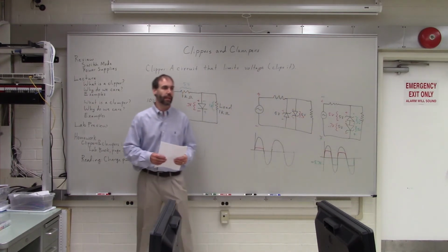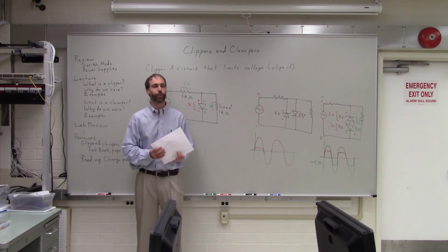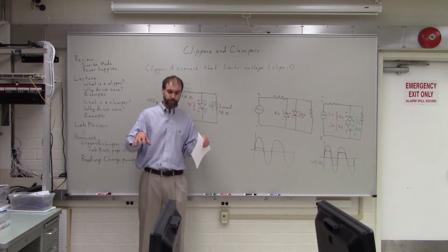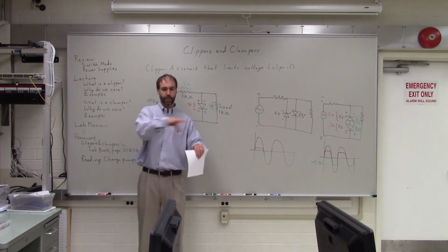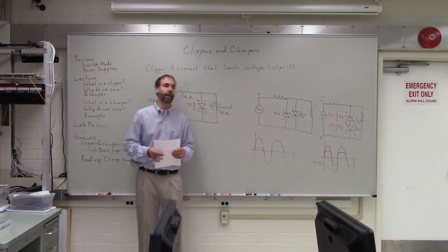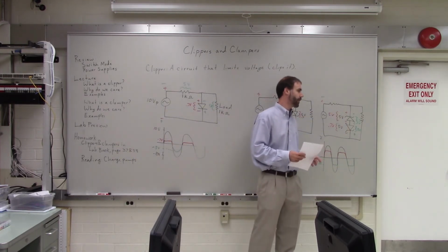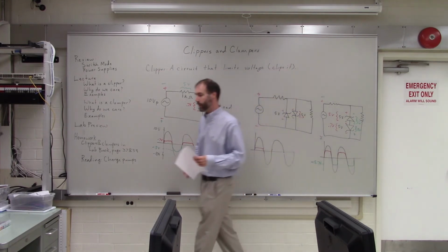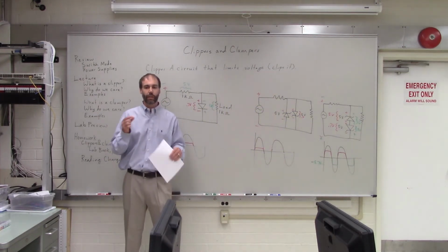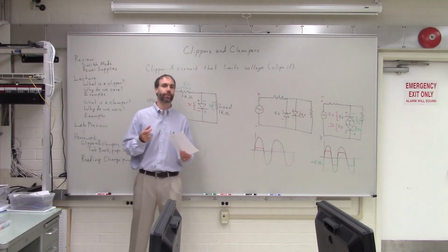Oh, cool. Yeah, that was a problem at a company that I worked for in San Diego. They had designed this robot that had a couple of motors on stages and they moved things around, but the electronics kept blowing out and they couldn't figure it out. What had happened is they had not put in one of these protection circuits. So every time the motors stopped, it created this big voltage pulse, and some of their components were not rated to handle that much voltage.